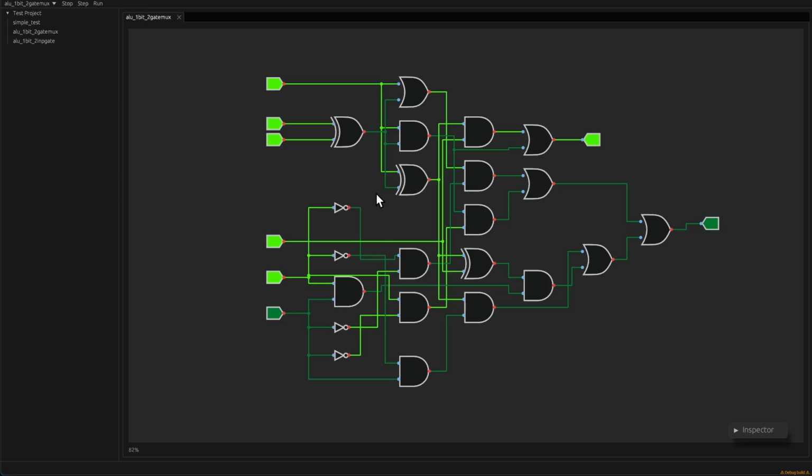Anyway, so there's automatic layout when you import Verilog. Verilog needs to be transformed by Yosys into a JSON file because I'm not implementing a Verilog synthesis engine here. I just want to be able to see the circuits that I make in Verilog. There's import from Digital as well. Currently, there's no way to add and remove components or change the wiring. It's just import only for the moment.